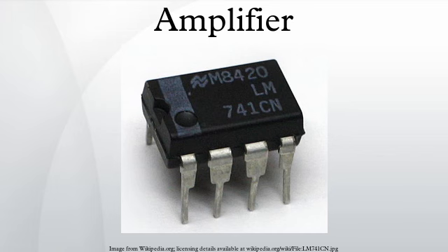Class H amplifiers take the idea of Class G one step further, creating an infinitely variable supply rail. This is done by modulating the supply rails so that the rails are only a few volts larger than the output signal at any given time. The output stage operates at its maximum efficiency all the time. Switched-mode power supplies can be used to create the tracking rails.